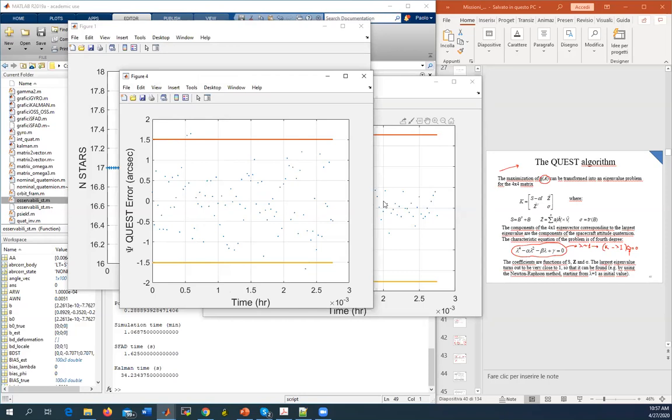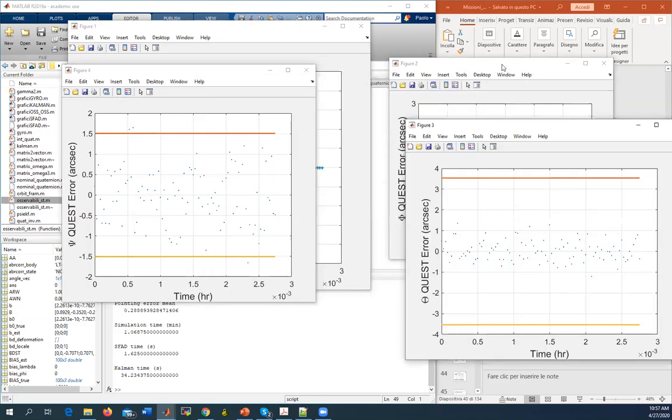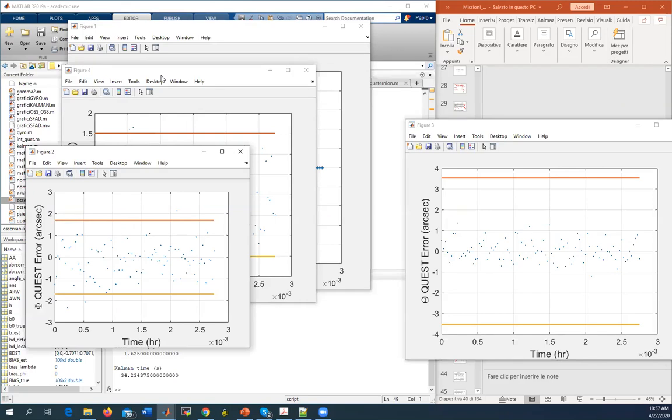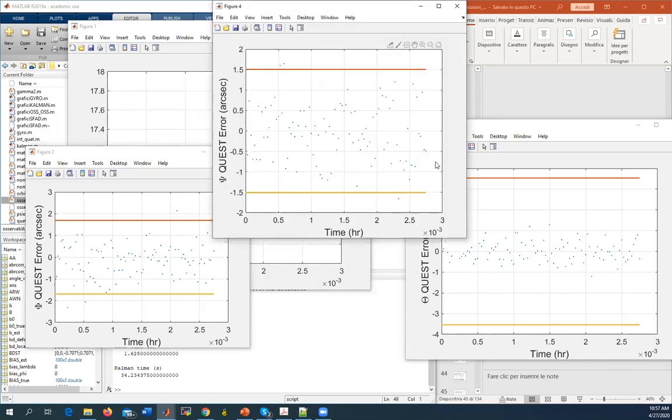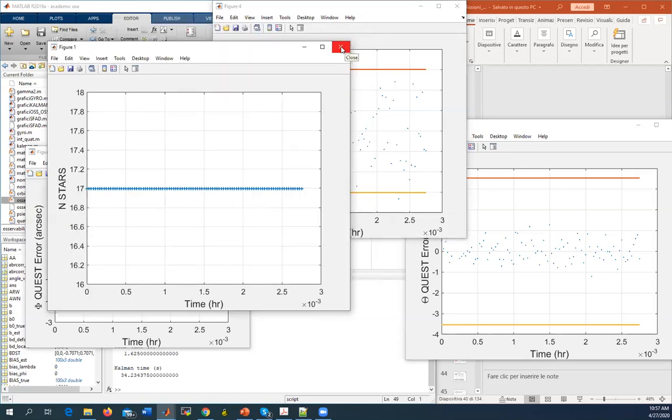Since it is a time integration of 0.1 seconds, at ten Hertz in frequency, we are assuming that the quaternion errors are small. And so you're able to determine the angle of the optical bench frame over time, as we have seen before. So delta theta is equal to twice the vector of the quaternions, right? So here the angle that you see is indeed assuming that approximation. So we are ignoring the scalar part of the quaternion, and we are assuming that the quaternion vector is directly related to angle variation, as we have seen in the slides.